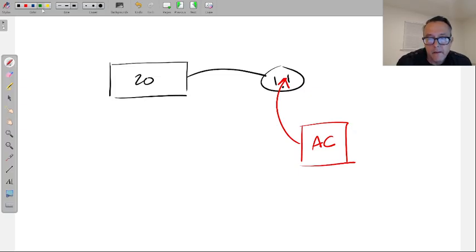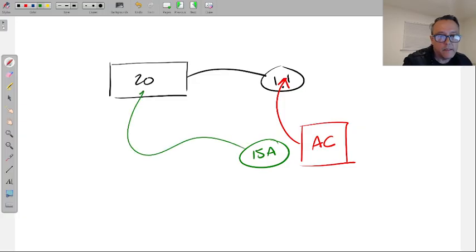But let's say, for example, when this air conditioner is on and running, its normal amperage that you'll measure in the circuit, let's give it some numbers, let's say 15 amps. Now, if you look at the breaker that's protecting this circuit, it's 20, so that's already good. And we'll assume that the wires can also hold 20.